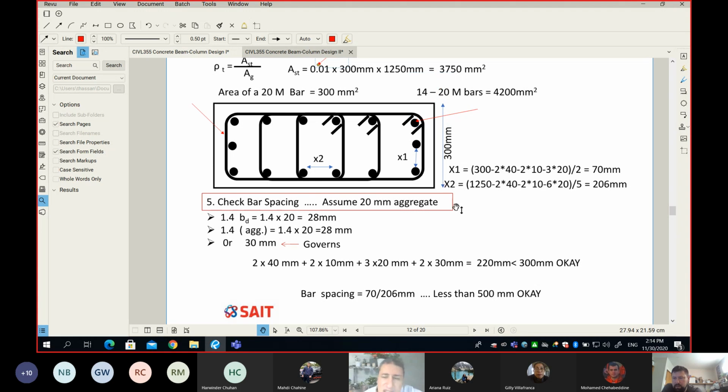And similarly, exactly the situation for all the corner bars. So the exterior tie will make all the corner bars, and we have 4 of them, okay. So we don't have to question them. They are okay. Now let me ask you, how about this guy here? Is it okay or not okay? Which is, by the way, the same condition as the one on the other side.